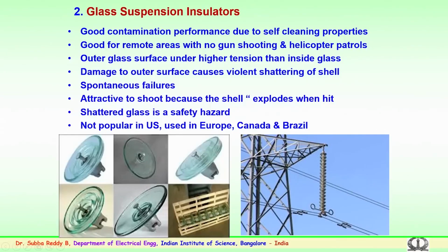When you carefully look at a glass insulator, you can see that, similar to a porcelain insulator, it also has metallic end fittings, a pin and a cap, and a glass shell with a particular petticoat depending upon the creepage length. You can see various types of glass insulators. These are normally without petticoats or sheds, usually used in desert areas where high wind could damage the petticoats or the porcelain or glass shells.